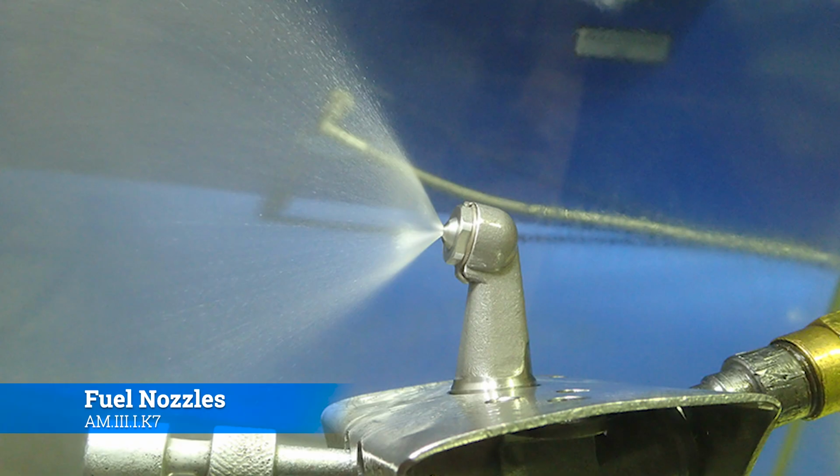That way you're giving the smallest group of fuel the greatest possible surface area, which is going to lead to the greatest interaction with oxygen, which is then going to increase combustion, because you need one part fuel, one part oxygen to make combustion actually happen. So if you can increase the amount of fuel that is available to mate with oxygen to create a flame, you're going to increase efficiency in fuel burn. So that's what this whole atomization process is all about.